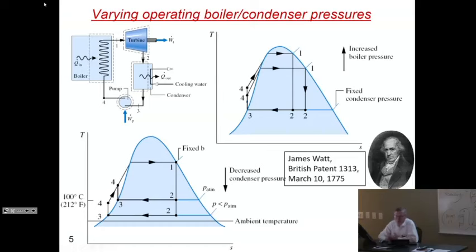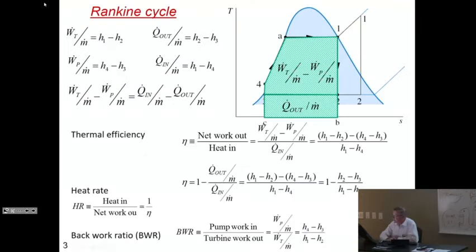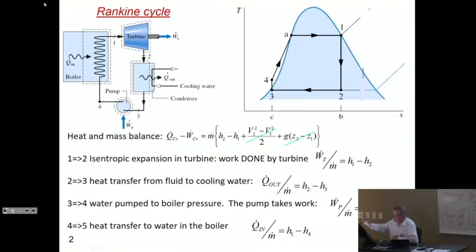And so we go back historically again, and we look at the very first engine, which was the Newcomen engine, which worked between a cycle where, let me roughly go here. This was roughly 100 degrees centigrade, and this was roughly ambient temperature. The reason is they couldn't take very much pressure on their old boilers, they would just blow apart. This is outside air, or outside temperature. So this temperature difference is small, so the amount of work that you could get off a Newcomen engine was small compared to the enormous size of the thing. And so you have these things that were sized like a building, and that would make 5 horsepower.